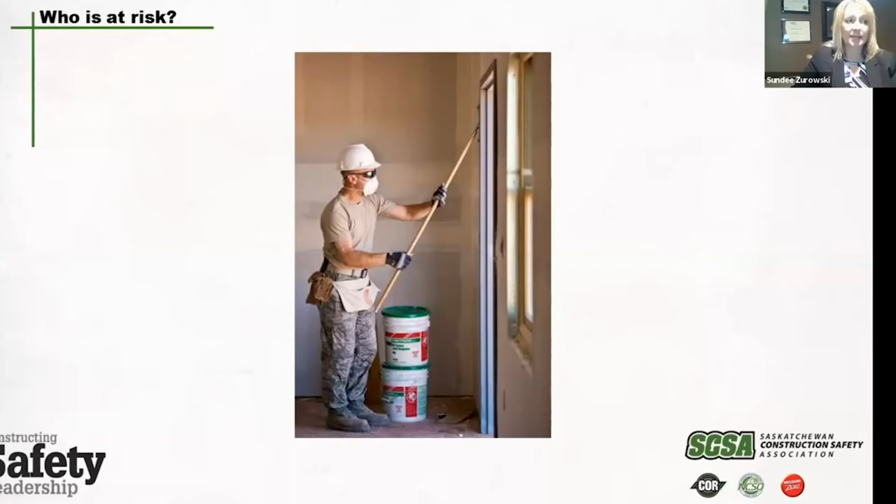Several lightweight sanding systems are available to help control exposure during drywall sanding. NIOSH study results suggest that construction workers' dust exposure might be reduced simply by changing from hand sanding to pole sanding. This change is even more important when working overhead. The pole increases the space between the worker and the sanding surface, which in turn reduces the amount of dust close to the worker's nose and mouth.